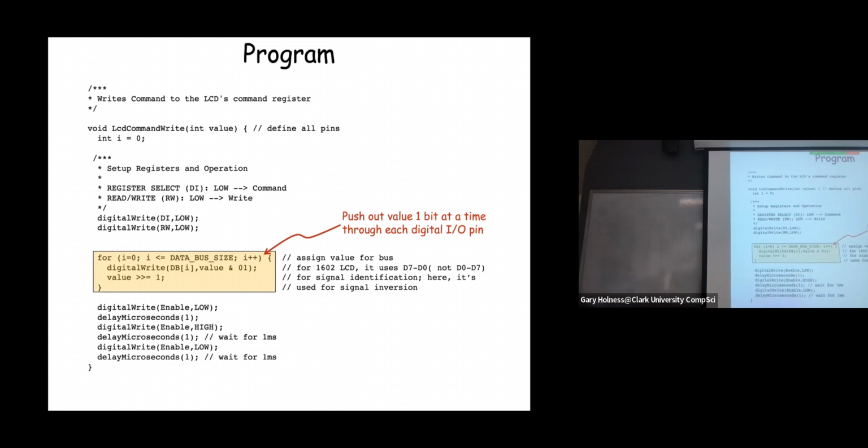So let me do that again. We have our device, and I'm calling DB0 the bus for the device. If I put a value on that device, it's either going to interpret that value as a command or as an ASCII code that it's being asked to display. Now, here's my Arduino, and it has I/O pin number 3. That's on the Arduino.